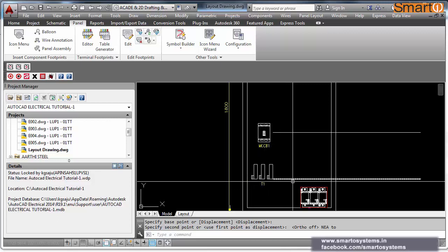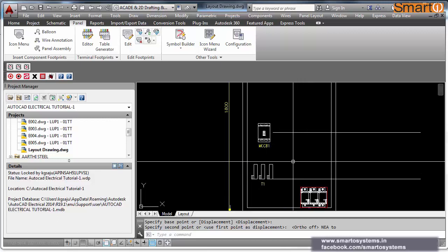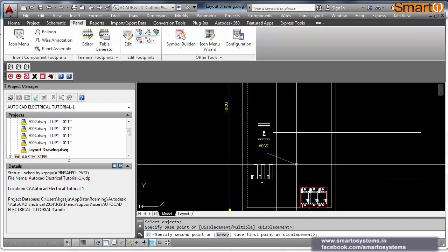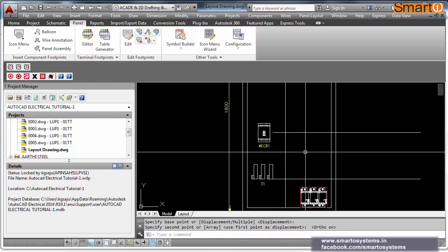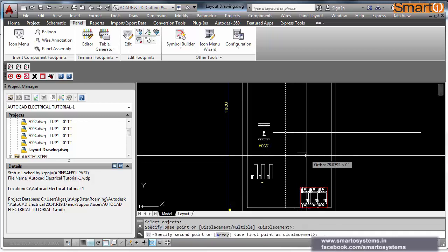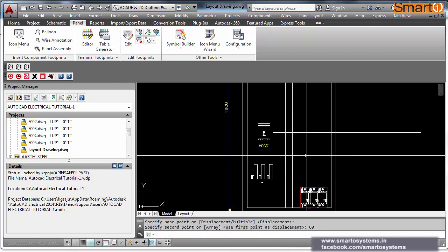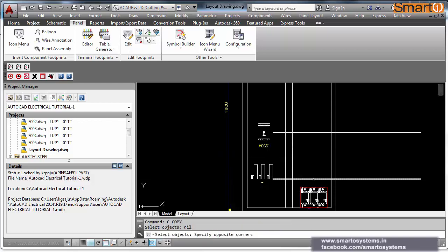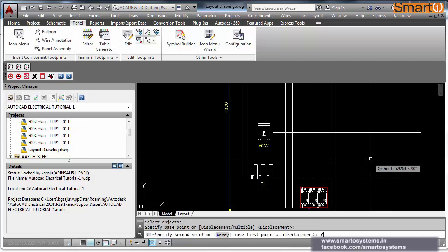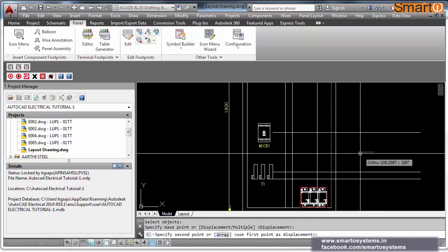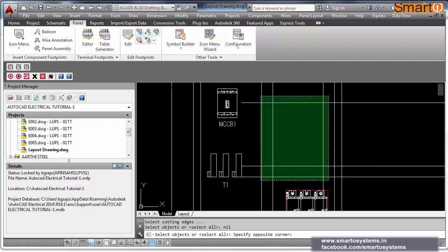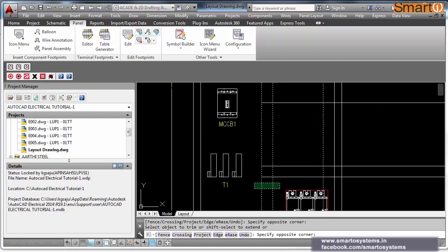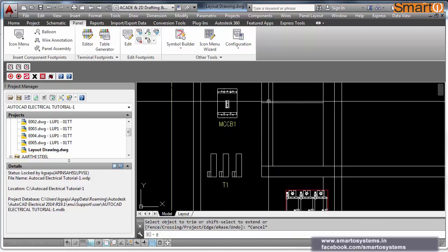So my cable comes here, goes to the MCCB. Now I have to bring that back to the choke. So what I will do is I will put some PVC channels, PVC ducts. They are also of standard sizes. Now I am putting a 60 mm duct here. I will put a duct here. Now see what I will do. I will trim all these things.